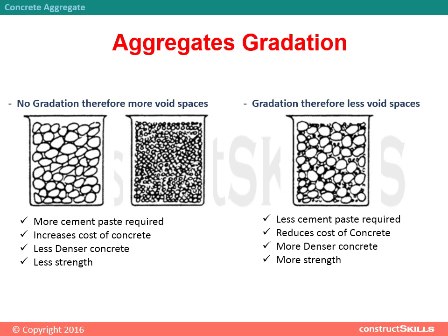If there is no gradation, there are more void spaces and more cement paste is required, which increases the cost of concrete.